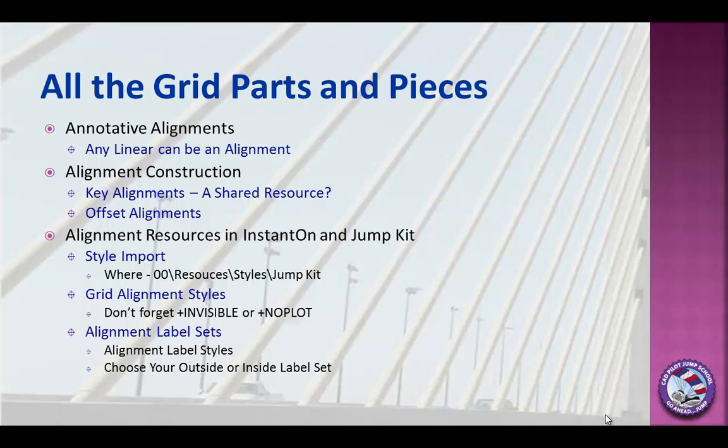We're going to talk about constructing grids inside of Civil 3D. It's a very simple, quick process that only requires a couple of unique styles. We're going to employ the idea of an annotative alignment, which simply means that really anything linear can be an alignment in Civil 3D. So we're going to construct the alignment and then build off a couple of key alignments,